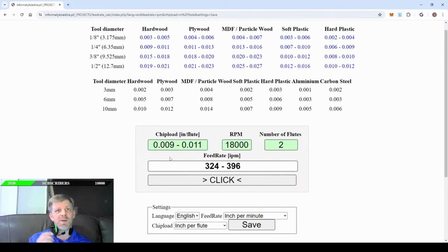If you were to take a look at an end mill bit and measured the distance of the flutes from the outside edge to the inside edge, you would notice that there's a core or a central part that is not covered by a cutter. Now, when you get over 30% of the bit, you're starting to crowd the center of the bit.